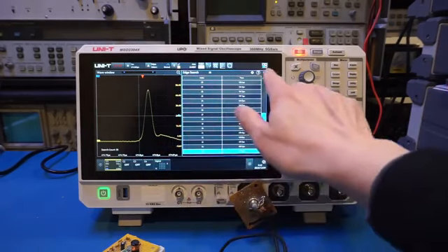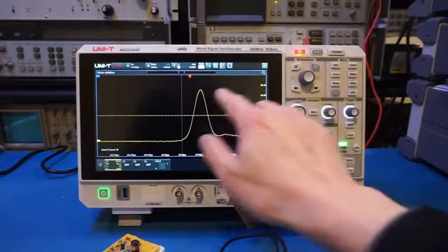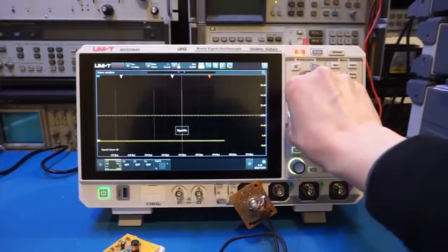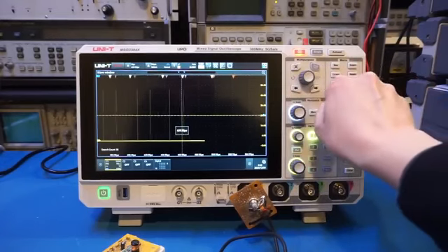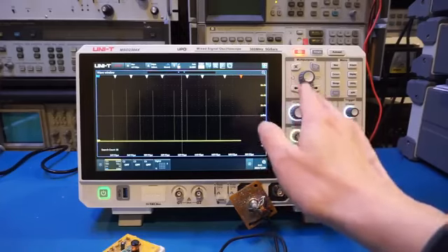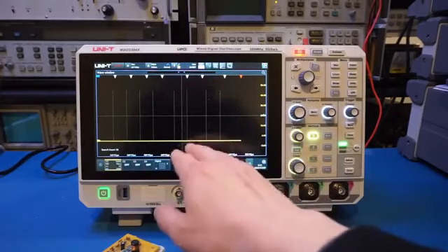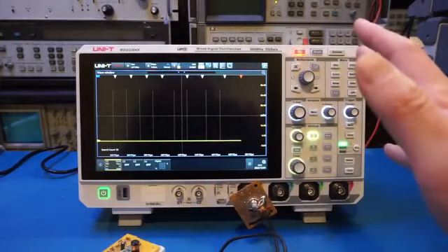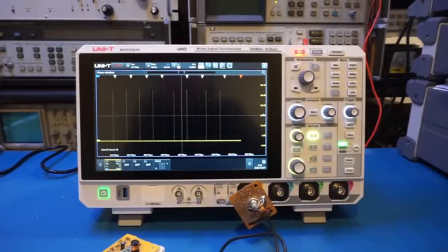You can see that if I just close this, we have this very short signal here. And if I zoom out, you will see we are actually not capturing that many signals here. The sample memory essentially is wasted, as for the majority of the time we're just waiting, there's nothing happening. And we do capture the signal here and there. So can we do better? The answer is yes. To solve this problem, many modern digital scopes have the segmented memory mode.